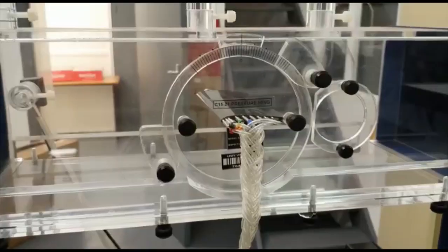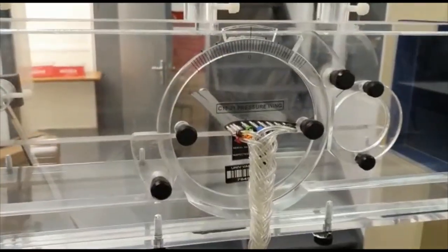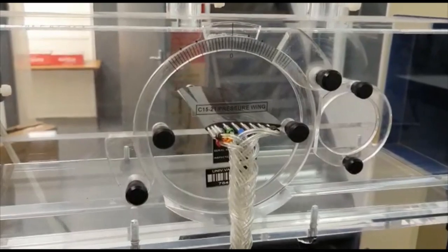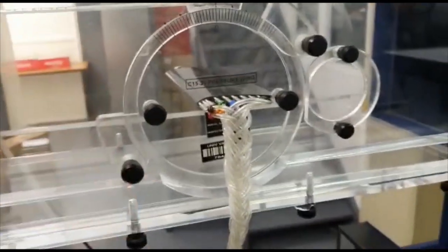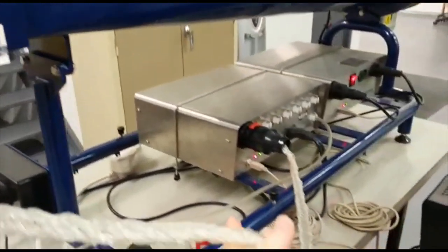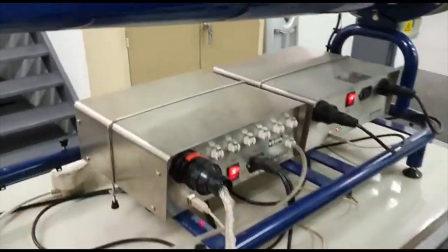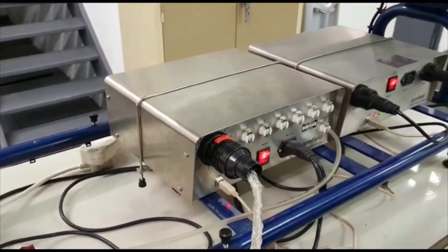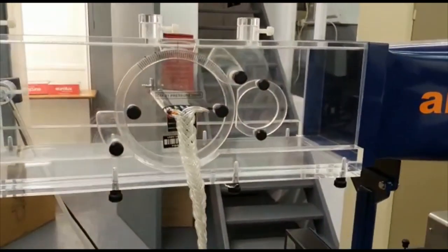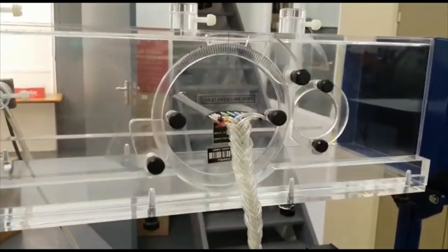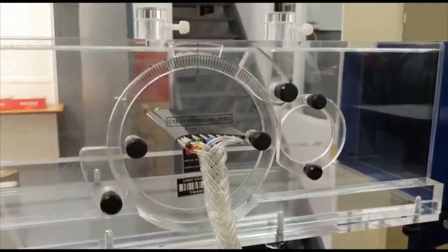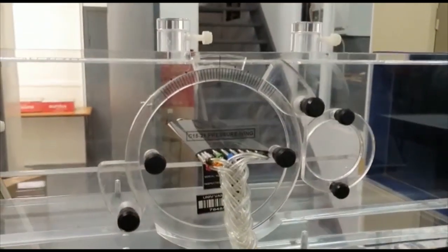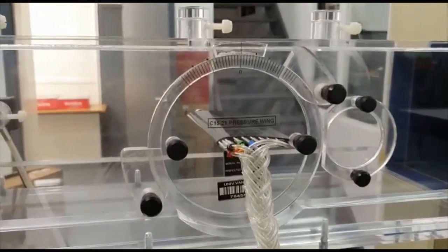In this case we're actually testing for pressure, so the values we get run through these pressure taps, and they attach to a manometer, which you would have learnt about in chapter 2, and through this we actually get volt readings, and from that we get pressure. We can use the pressure results that we get to translate that into pressure coefficient, which is a non-dimensional value.